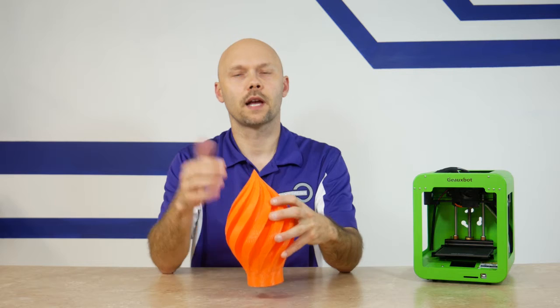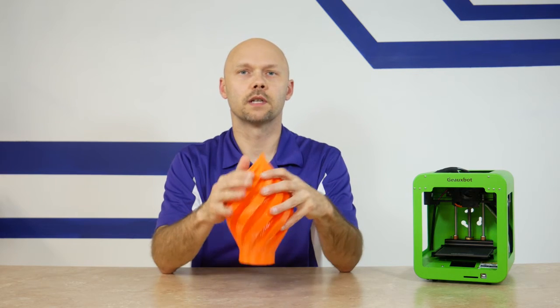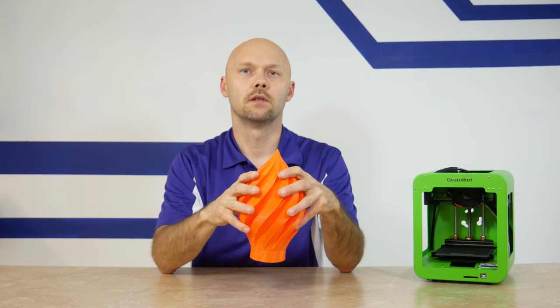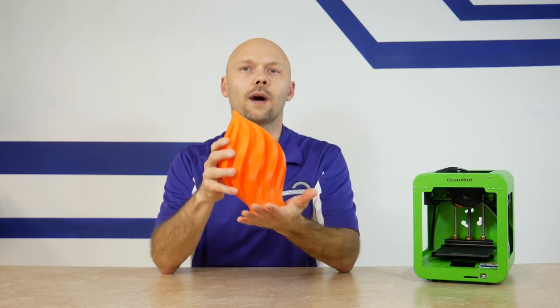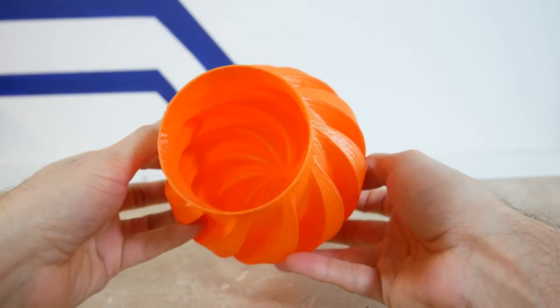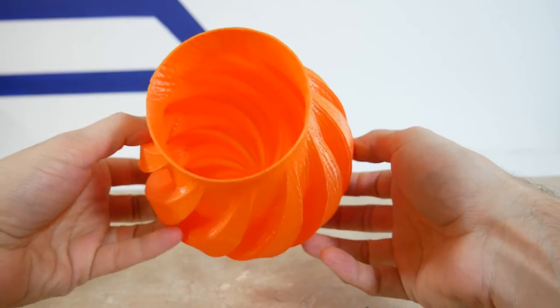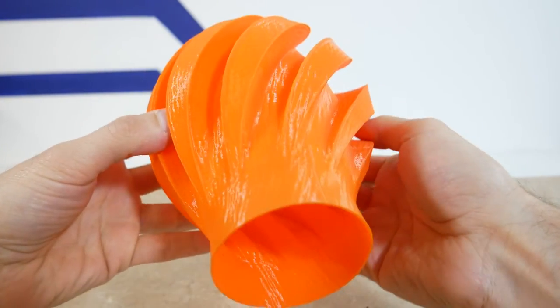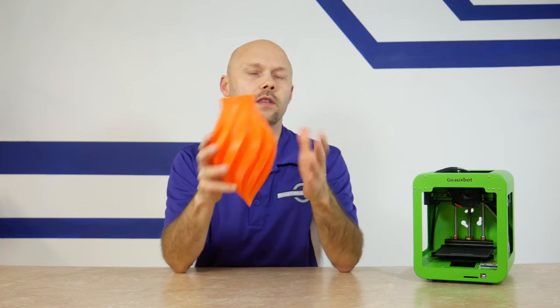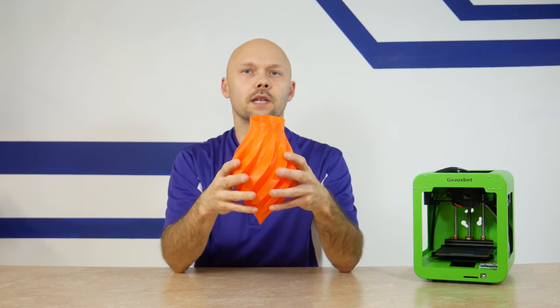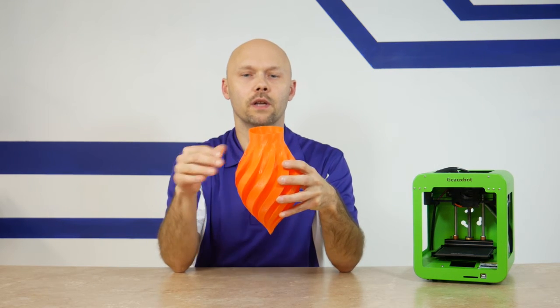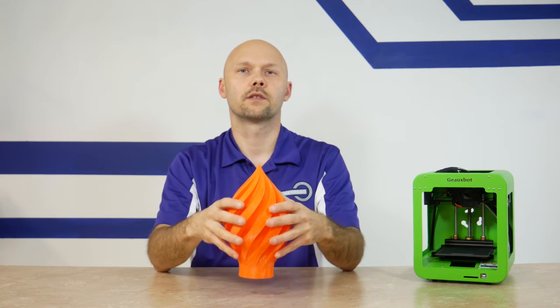So what we did is we actually went in the program and said 0% infill. That means no infill at all. We also said no bottom. So what happens is it was 3D printing, it didn't create any infill and it didn't create a bottom. So now we can put a light in here and actually light it up for Christmas ornaments. And you can do the same for a vase. The difference is for a vase you would say no top, no infill, and then you would have a vase that you could put things in. We'll show you how to change those settings right now.